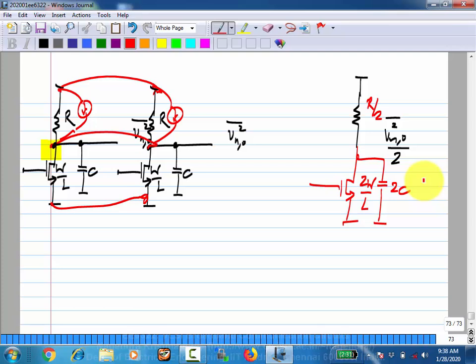The other one was contributing, let's say, only 1%. Maybe you can actually scale it down so that it contributes more. Its contribution increases, but in the overall contribution, it may go from 1% to 2%. It's not a big deal. So this scaling is very important, and when you are optimizing circuits, this is something that you have to do.